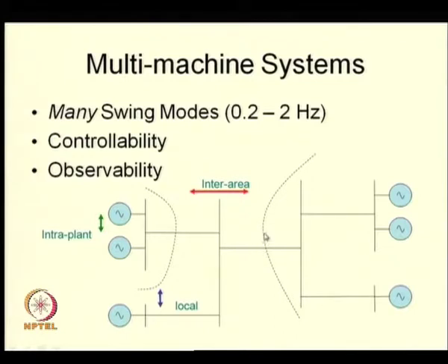When you are trying to use this variable reactance device, the question may arise, can I use this variable reactance device to damp out or improve damping of the intraplant modes? Very unlikely. The point is, you have to worry about the classical concepts in control systems. The intraplant mode is very unlikely to be controllable by reactance modulation present on this line here. So, there is an issue of controllability.